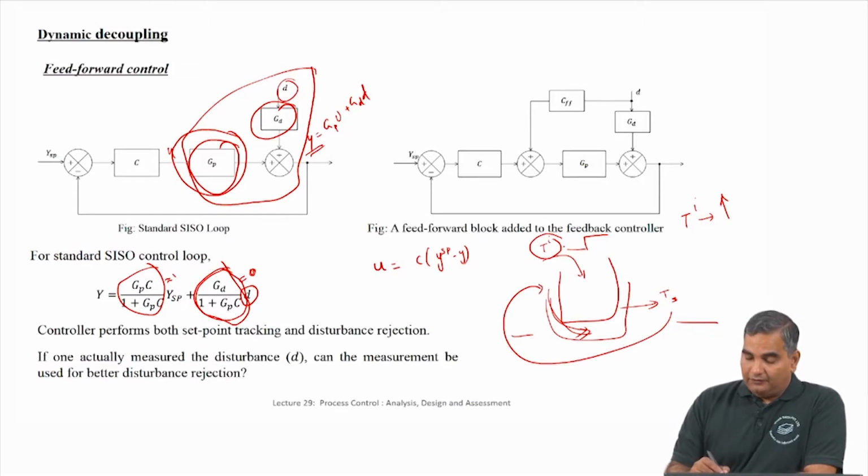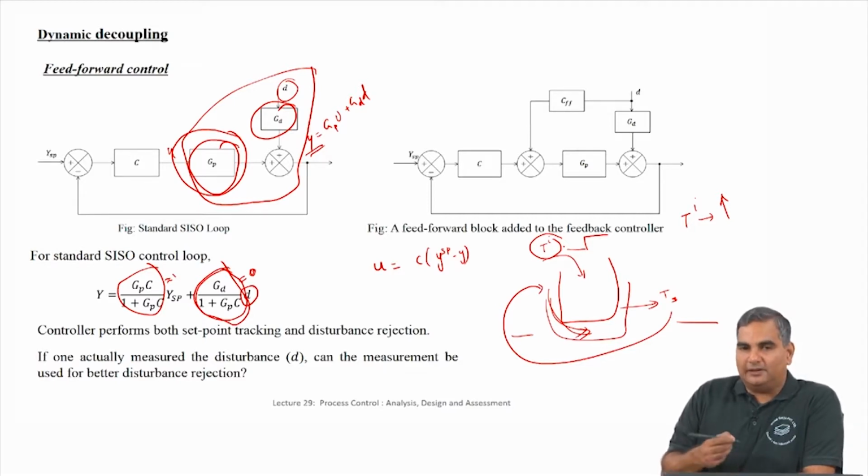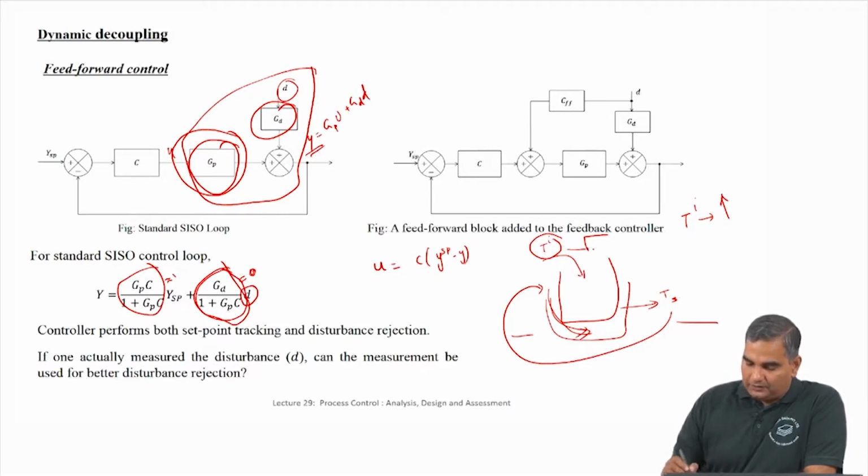However, after this Ti has increased, for Ts to show a change, it is going to take some time, because I have already said many of the systems have at least some little bit of time delay, number one, and there is also dynamics associated with it. So, basically, if let us say this is the point at which Ti changes, you might still not see the change in the system temperature for a while because of time delay, and then when it starts, if it is a first order or second order system, it is going to slowly change something like this.